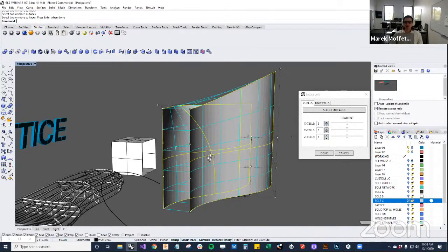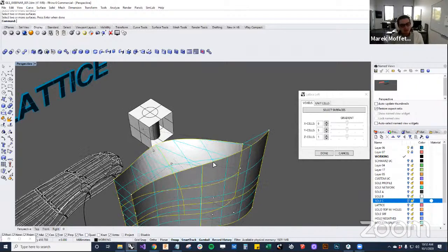Again, I don't really know what your geometry is like, but the biggest high-level hint I can give is to optimize your model for GLS by designating the zones you want to be latticed, and then rebuild those zones you want to be latticed as single surface data. Okay.